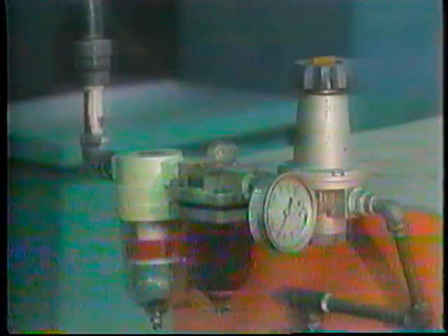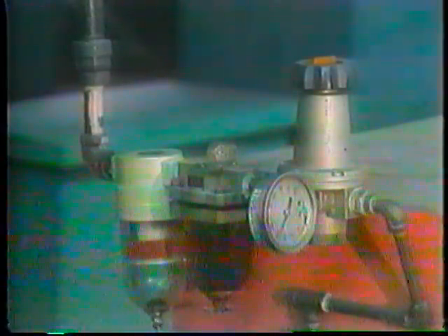All the oil delivery systems we've described so far allow the oil to be recycled. That is, the reservoir is also a sump where oil returns after it has been delivered to the bearing parts. Some oil delivery systems use the oil only once. This drop feed oiler is an example. It delivers oil one drop at a time, and its external reservoir must be refilled fairly frequently.